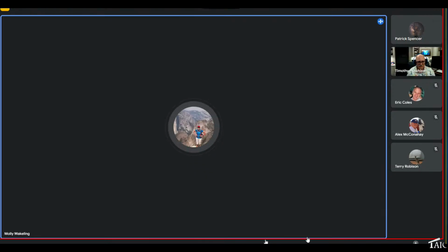Let's see. Shoot. You want to talk about dark frames a bit with the newer CMOS cameras? Some argue that you don't really need dark frames as much anymore with the lower noise on the newer cameras. What's your take on that? Well, I would say that the importance of dark frames for CCD cameras was much greater. Because why? Because the dark current was much higher, right? So is the impact less? Yeah, I think the impact is less.